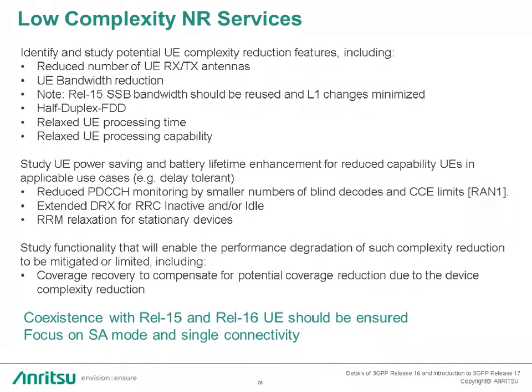Another aspect is about studying the UE power saving and battery life enhancement for reducing the capabilities wherever the cases are applicable, depending on the application of the device. Reducing the PDCCH monitoring, extending the DRX for RRC inactive and idle, and again reducing the RLM reporting for stationary devices.